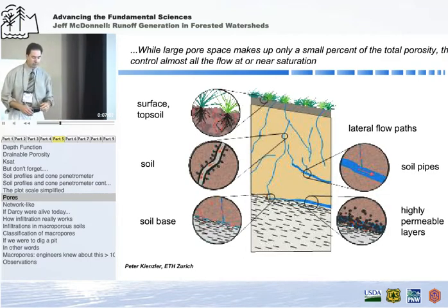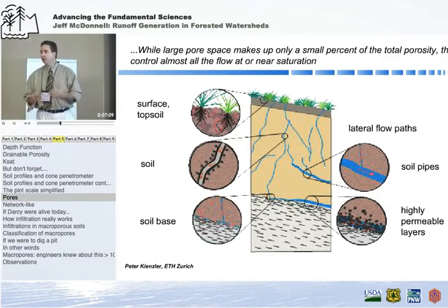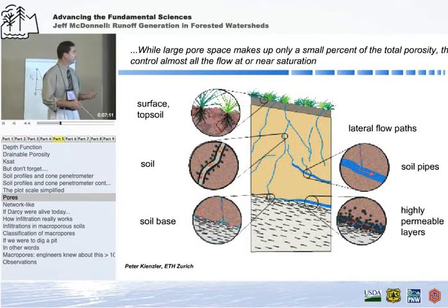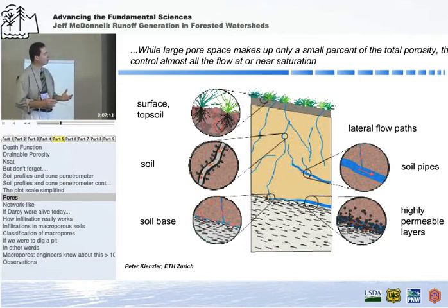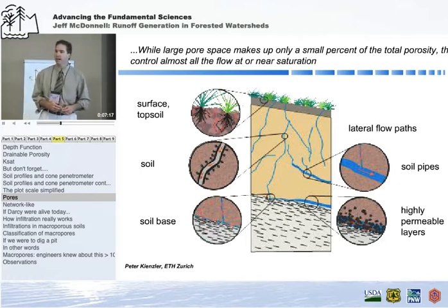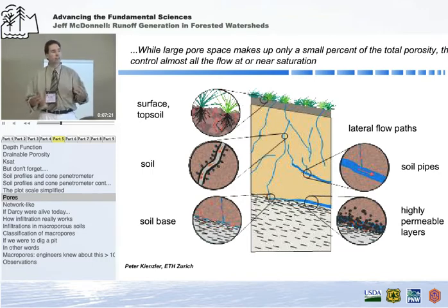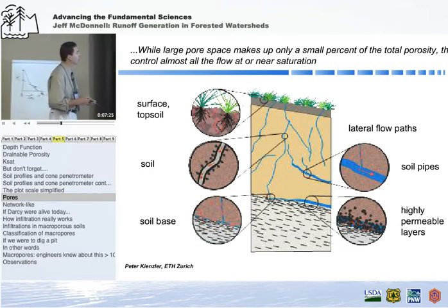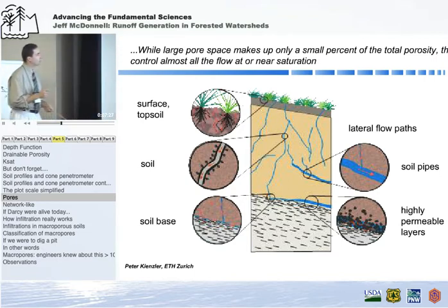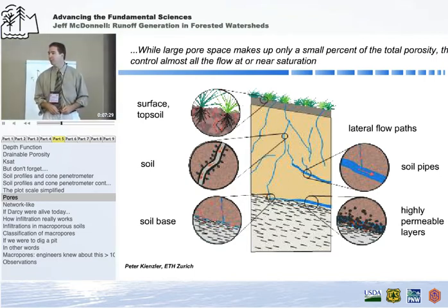Now, against this backdrop of matrix conditions at the plot scale are the preferential flow components. And this is rarely addressed in the kind of hydrology texts that we look at, and variable source area theory and a lot of our widely held mechanisms don't look at preferential flow in detail. But this really does control the behavior of our forest soils when things are wet.